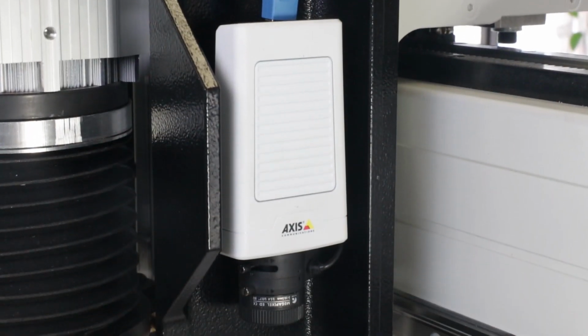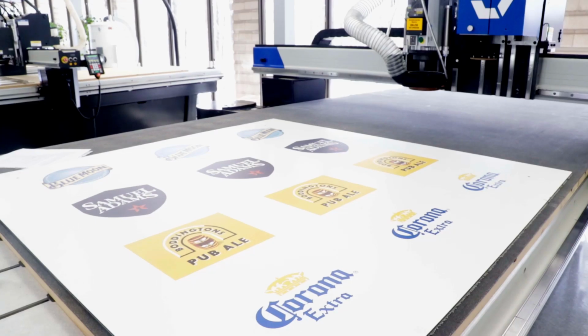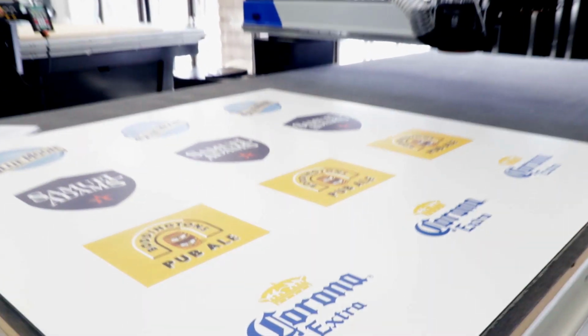The AVS camera is what's used for finding the registration marks. We have 3 different dots, an A, B, and C dot. You can use them in any combination you see fit. On this particular job, we use 4 C dots. Dots are typically about 1/4 inch in diameter. We want to get good contrast between the dot and the surface.